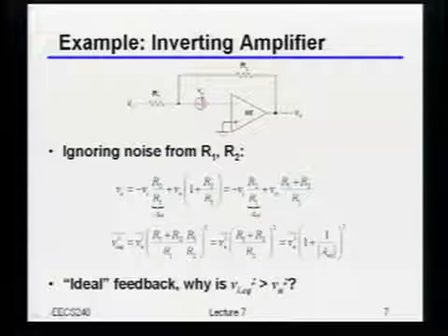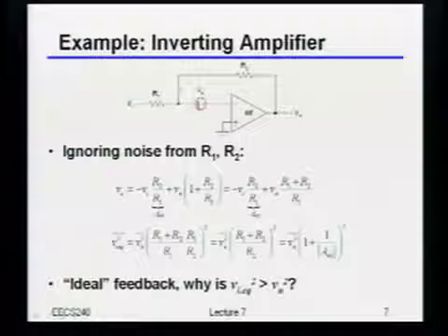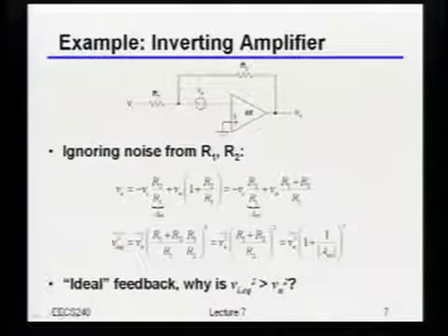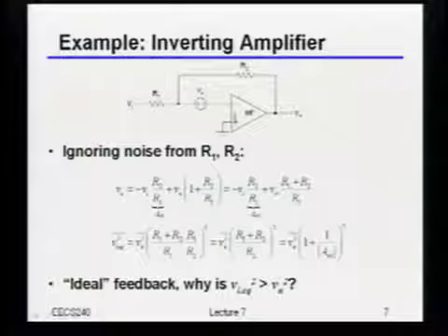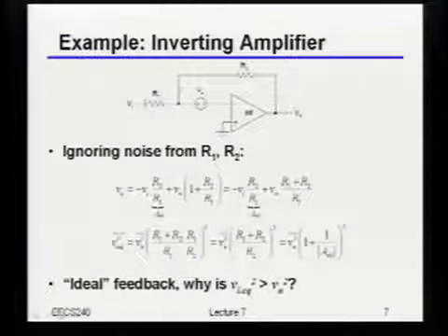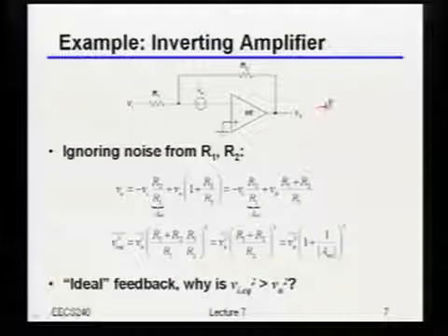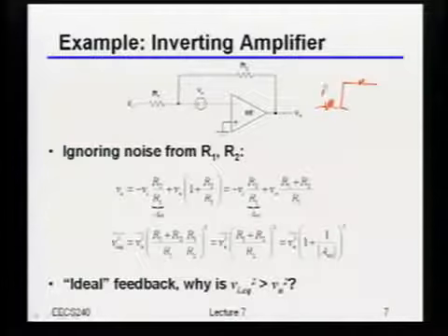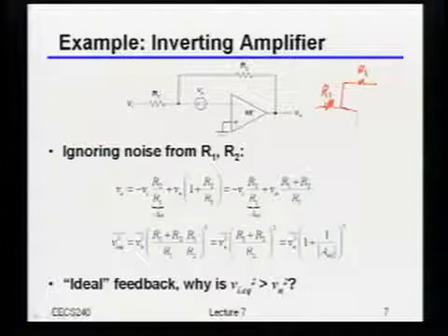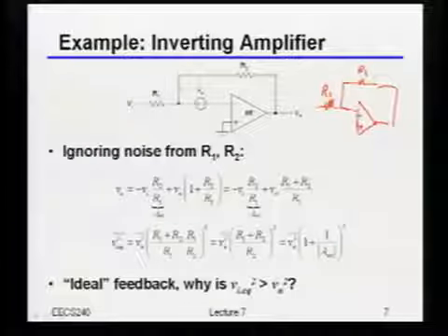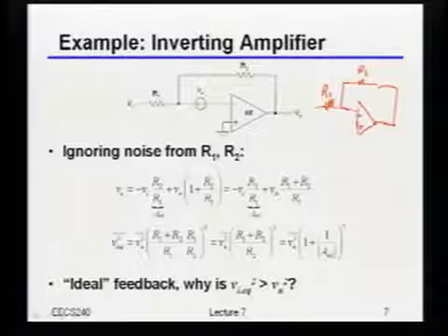So from the standpoint of the noise signal over here, it's maybe not immediately obvious, but the noise signal is connected in the almost non-inverting configuration, right? Where the gain is actually 1 plus R2 over R1. Just in case you don't believe me, the way to see that is the following. Everyone should agree that because it's noise, it doesn't matter which polarity I connect it to, right? So I can always say that the voltage is reversed.